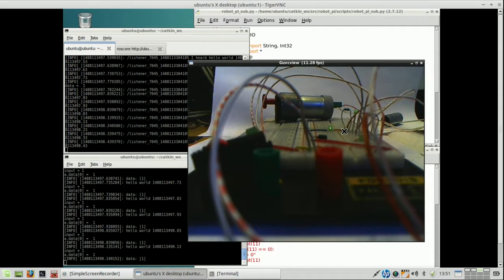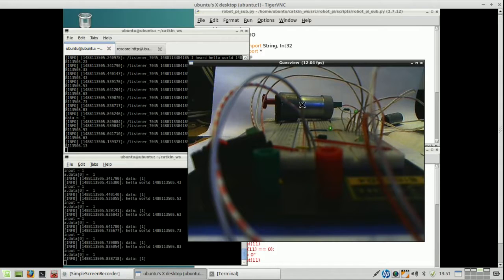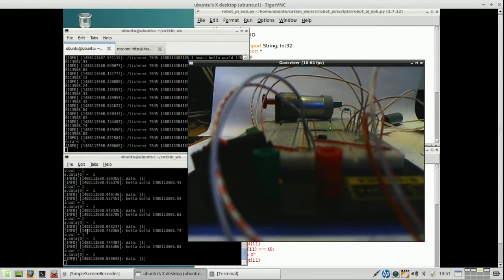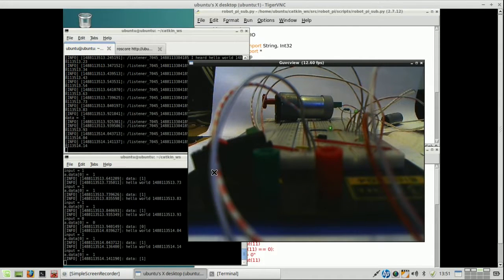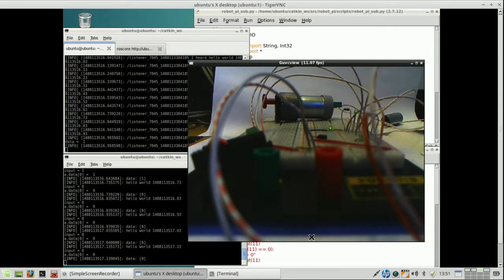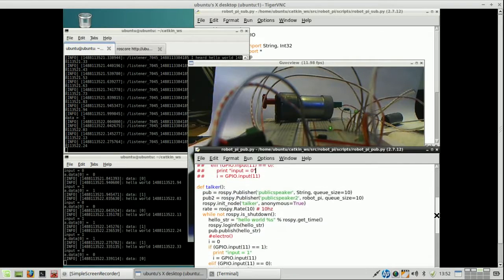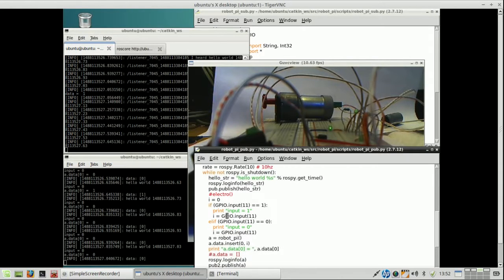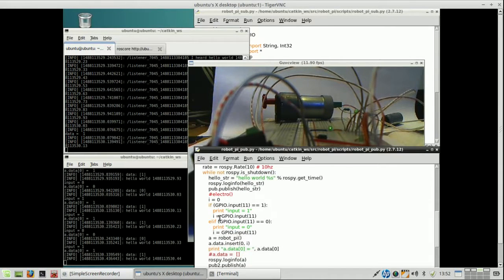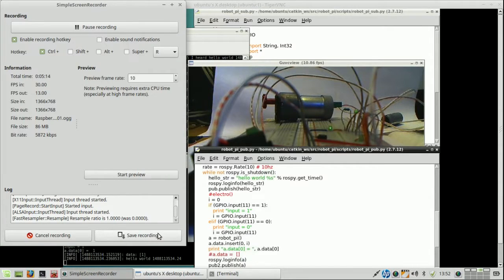And yes, that is a problem. Well, it will work correctly somehow, because one would indicate that the motor works, but since this is not corresponding correctly with the switch, there's an ouch. So I need to look into the software. That is most likely the case. And this is the software reading the switch. So let's take a look at it.